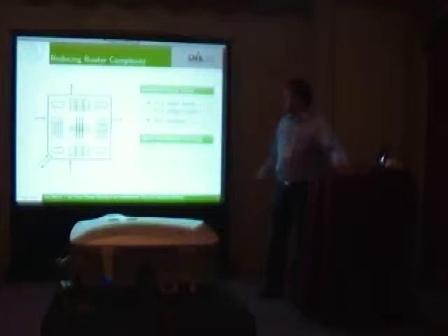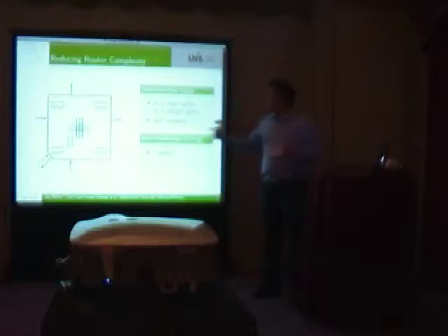And we use a different routing, which is called semi-bufferless. It's not completely bufferless, but it uses a lot fewer buffers than a conventional router. So there's only 1 buffer per router. And since everything is simpler, you need a much simpler arbitration logic and flow control, so the logic becomes much less.